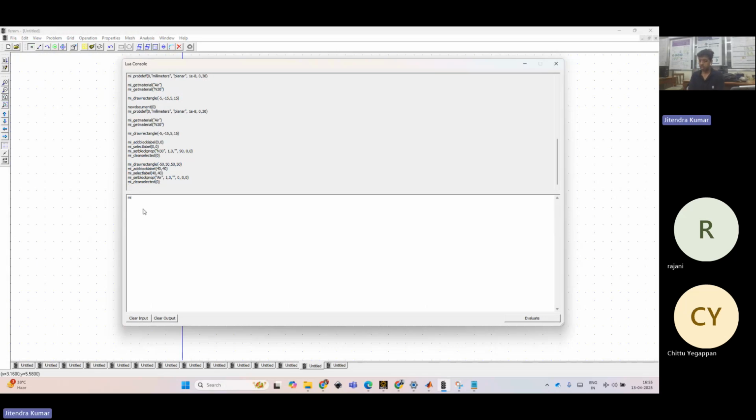So we could enter the next line of code as mi save as something if you want to save it. Save as bar magnet. Okay, now the important thing is to analyze, right? That will run the simulation. So mi analyze, yeah, nothing is magnetic on it. Then mi, these are the lines to solve it. Mi load solution.